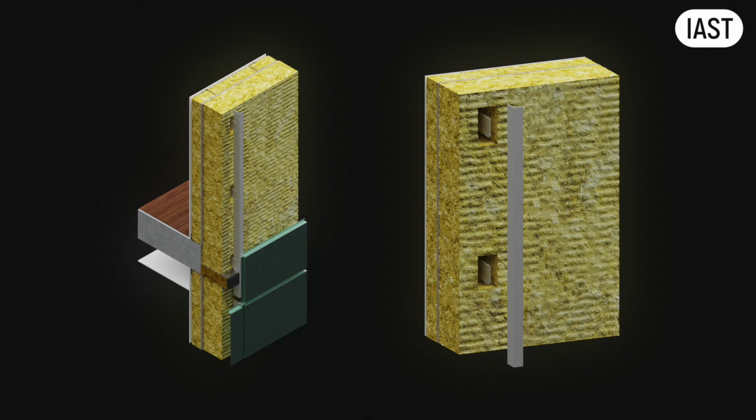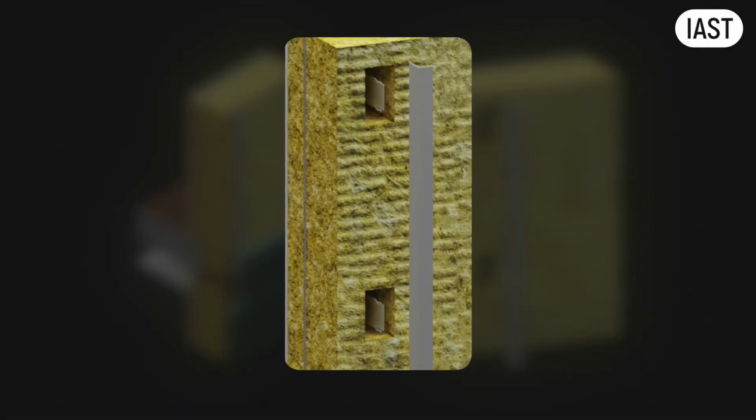First, installation gaps. A void at the board edge. Insulation not cut tight around penetrations. Each one bypasses the insulation entirely. The heat finds the gap and goes straight through. Once the wall is closed, you cannot fix this. It must be right during the installation.